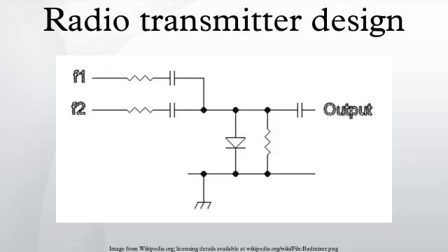Linking the transmitter to the aerial. The majority of modern transmitting equipment is designed to operate with a resistive load fed via coaxial cable of a particular characteristic impedance, often 50 ohms. To connect the power stage of the transmitter to this coaxial cable transmission line, a matching network is required. For solid-state transmitters, this is typically a broadband transformer which steps up the low impedance of the output devices to 50 ohms. A tube transmitter will contain a tuned output network, most commonly a PI network, that steps the load impedance which the tube requires down to 50 ohms.